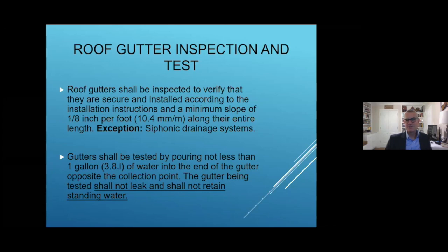So the gutters, to test them, you've got to dump at least 1 gallon. It doesn't hurt to do more, but at least 1 gallon at the far end of the gutter, and you've got to see that it goes to the intended collection point, and you've got to see, like at the bottom I've underlined, that it doesn't leak and it doesn't retain standing water. So that's the critical part of that inspection.